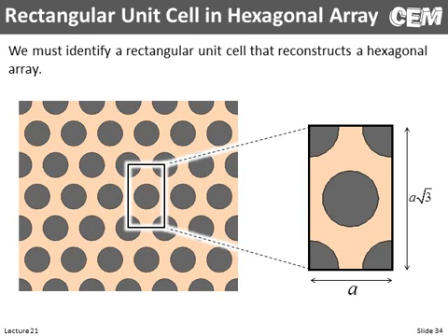However, if you're just running one quick simulation or just a handful, you don't have to bother with reformulating your rigorous coupled wave analysis code to handle that. Although I will say, if you ever did that, it's a little bit of a mind thing maybe to do, but in the end you change very little of your code when you go from a rectangular RCWA to a generalized symmetry like hexagons. So the implementation is actually quite simple, but I wanted to point out here we can model hexagonal gratings even with a rectangular code, but there is a small hit in efficiency.